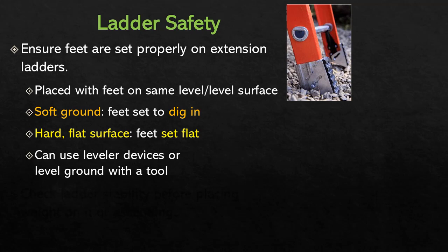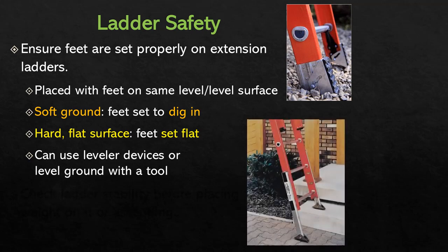If the ladder is on a hard, flat surface, you want to set the feet flat on it. Again, that's exactly as you would imagine. Most ladders have a couple different settings on them where you can set them flat or you can set them to actually dig into something. But regardless, you need to make sure that you use a leveler device or some other tool to ensure that the ladder is set right or the ground is sort of built up in such a way that the ladder goes straight up and the feet are level.